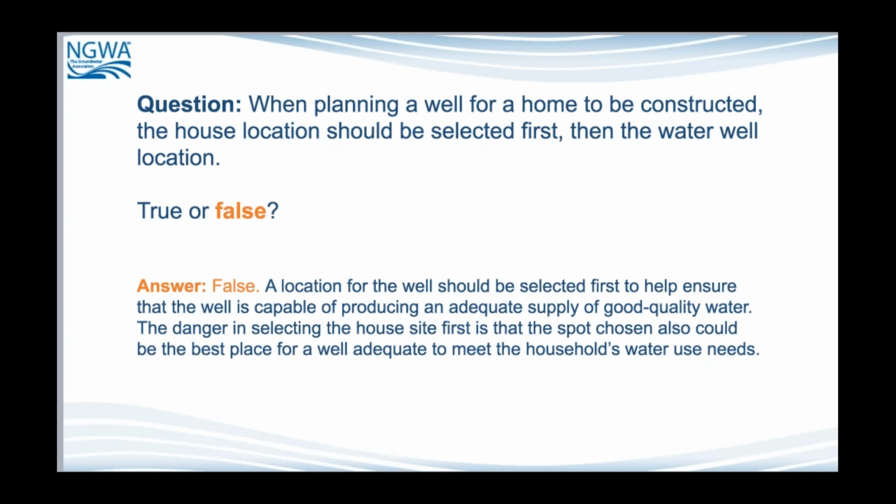A lot of times I have to do specific testing to see what the soils are, and then the septic sometimes is locked into where it has to be based upon the drainage of your particular property, either the slope like we talked about, or the actual materials that the water is going to have to flow through to allow your septic system to work properly. So including where you're looking at moving your water well, you may also want to be talking with your septic contractor as to where he has to locate his, because you do have to keep enough distance between the two.